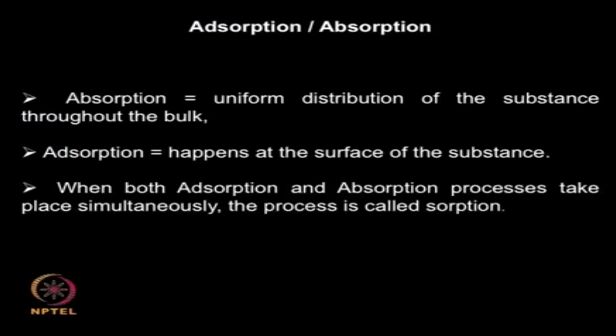For example, carbon dioxide gets absorbed in ethanolamine solution or sodium hydroxide solution, whereas in adsorption the solute gets attracted to the surface and it remains on the surface. So it is a surface phenomenon. The rest of the bulk of the solid does not have the solute present. So that is the main difference between absorption and adsorption.